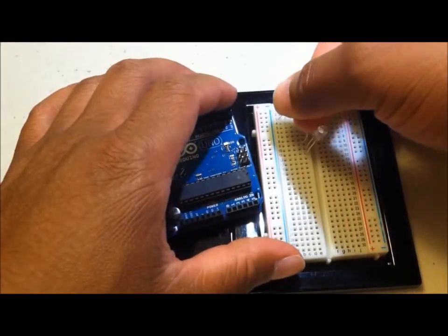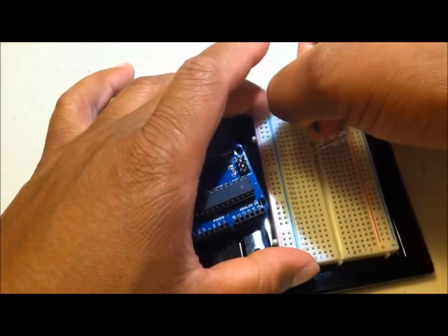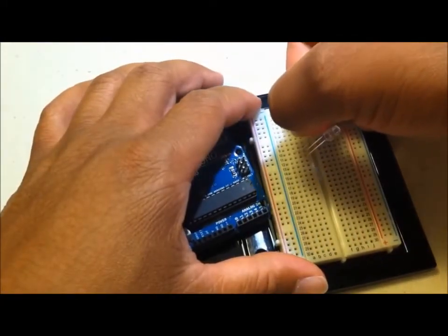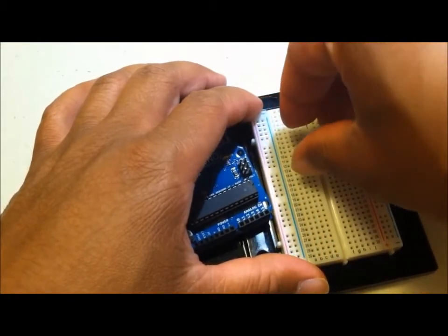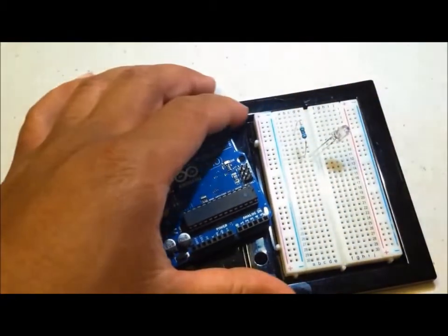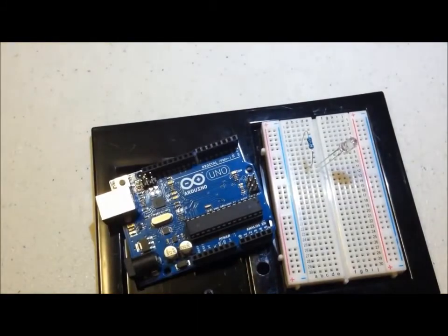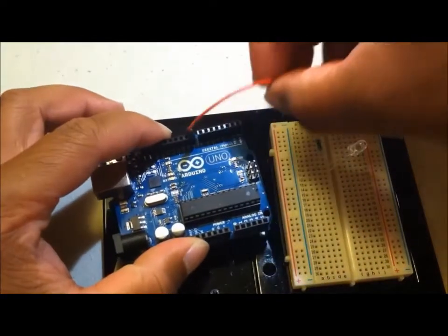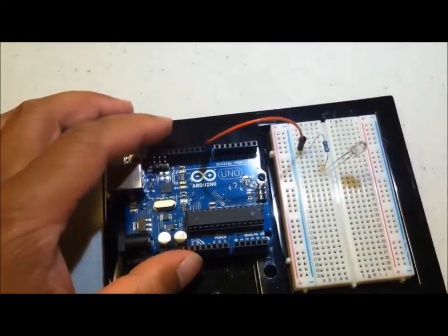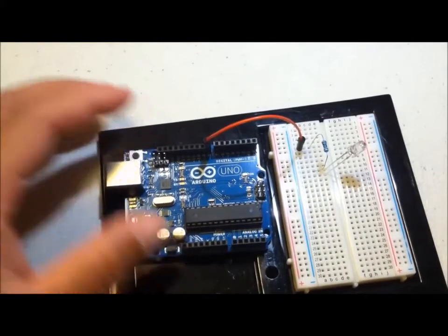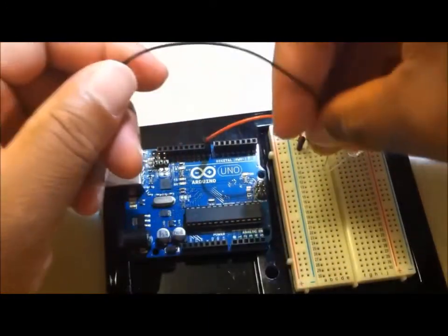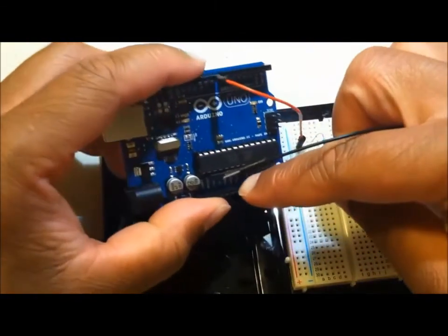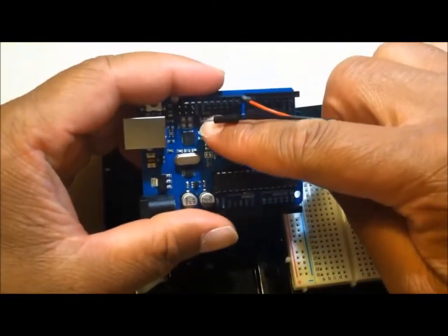When you use LEDs, you always want a resistor in series with the LED. This decreases the current flowing through the LED, because if the current is too high it'll just burn the LED out, which actually happened just the other day. And we want to connect this circuit to pin 8, which is basically, in this case, our input. Then connect the other end of it to ground to essentially complete the circuit. And ground is the 2 ground nodes right here and 1 over here.